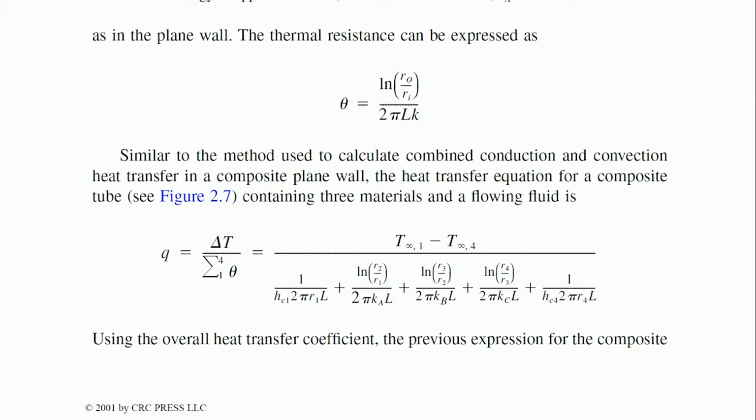The only thing we do not know is that often this K is not very well defined, because occasionally K is also dependent on temperature itself, and a lot of it depends on the fabrication process. In certain fabrication processes, the materials are compacted. Typically, the best example is forging. If something is forged, the conductivity will be high. And if something is made by some other, normal process, especially if it is gravity die cast or gravity mold, there are always microscopic voids inside, and that will not have the same K, though it is aluminum.